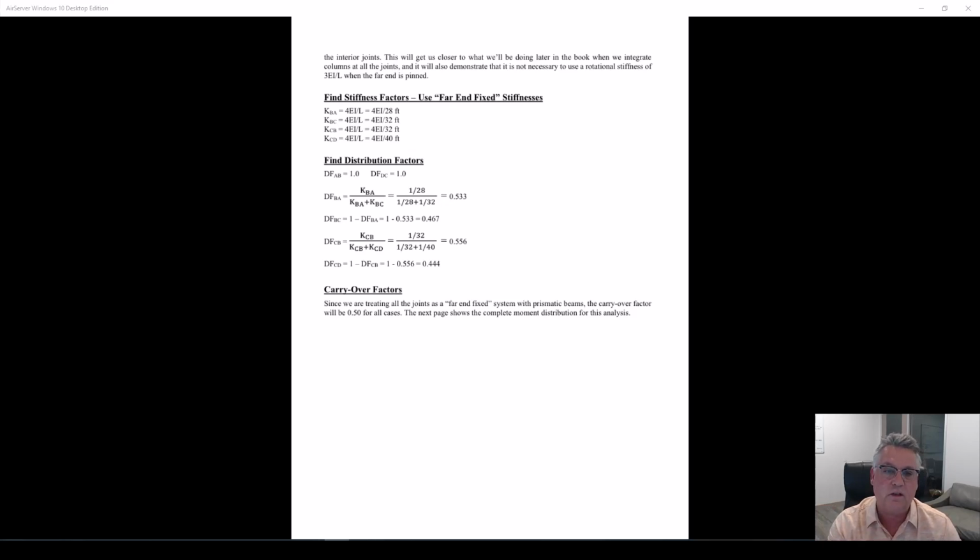Everything we just did is the way I want you to approach the homework assignments, the exams. Just use the 3EI over L to the far end pinned. Use the 4EI over L on the internal spans, and you'll be fine. We'll just stick with that. There is another way to do this, and maybe this is the way you learn, so I will present the fact that at least I'm aware that you can do that.